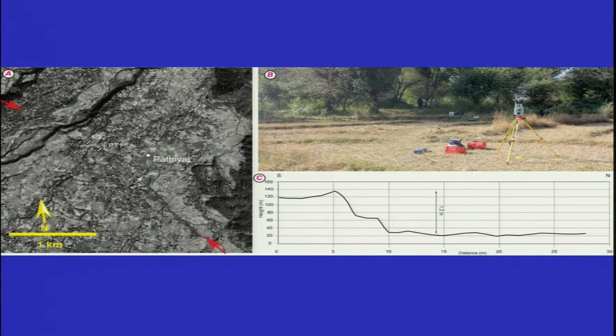If the feature is very sharp, you will be able to pick up this deformation even on the satellite photos. And nowadays, with the advantage that you have the digital satellite data, okay, you have the data on your PC, you can enlarge this area of your interest, and then you can view this in 3 dimensions. That will increase at least the resolution, which will help you in identifying even the minor features which are having height less than 1 or maybe around 1 meter also.